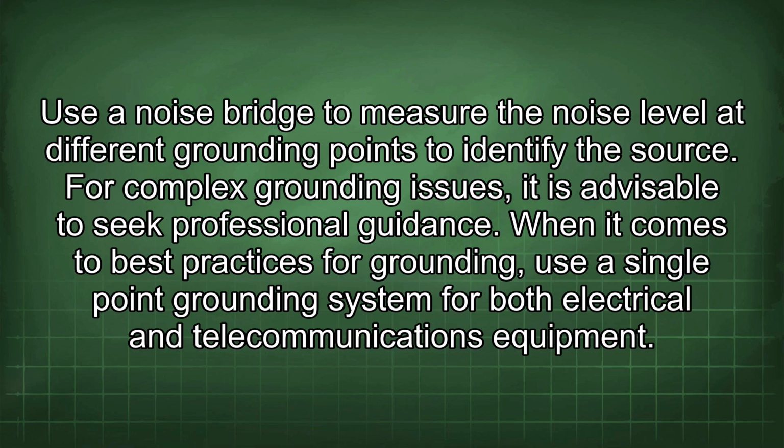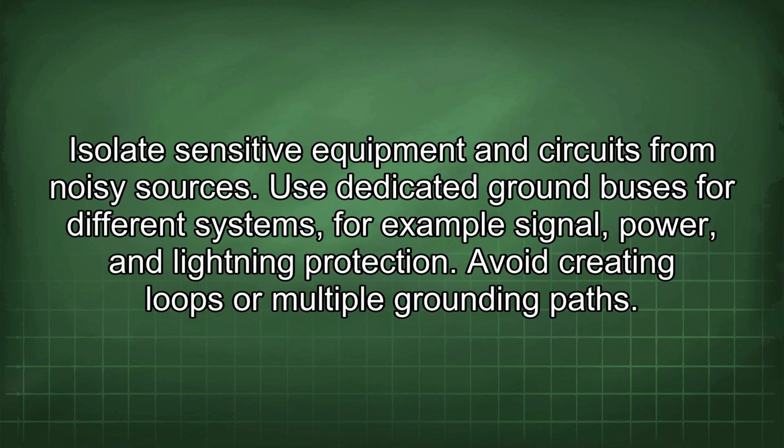When it comes to best practices for grounding, use a single-point grounding system for both electrical and telecommunications equipment. Isolate sensitive equipment and circuits from noisy sources. Use dedicated ground buses for different systems, for example signal, power, and lightning protection. Avoid creating loops or multiple grounding paths.